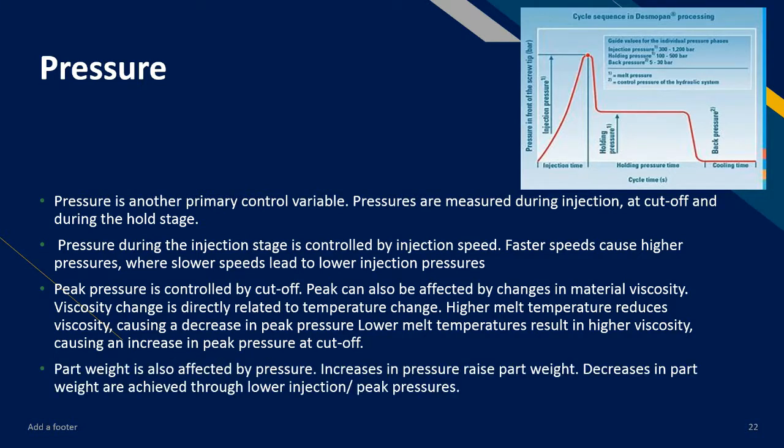Part weight is also affected by pressure. Increases in pressure raise part weight. Decreases in part weight are achieved through lower injection and peak pressures.